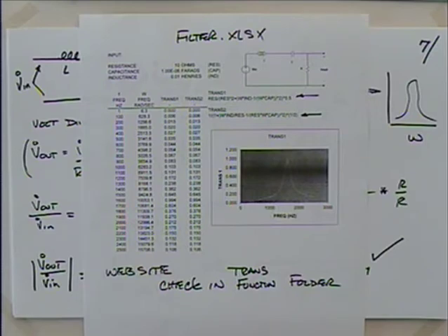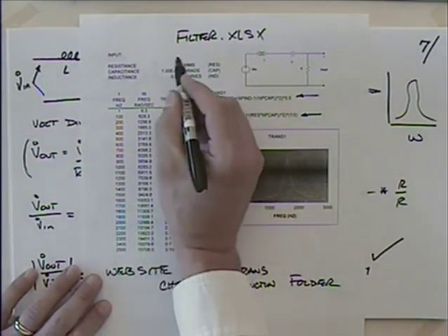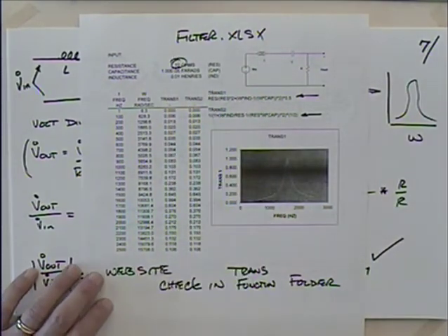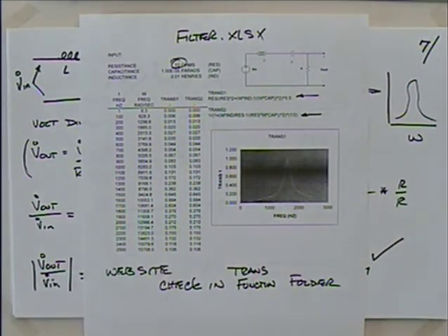Bandpass filter, right? Once you get something built like this, the really cool thing is if you start messing around with the resistance, if you increase the resistance, it's going to start to open up the bandwidth, which is going to be a problem. Particularly 10 ohms. Does that seem like a realistic resistance?